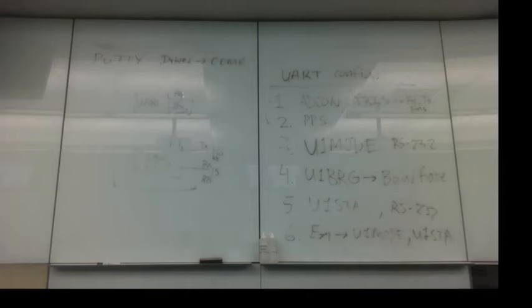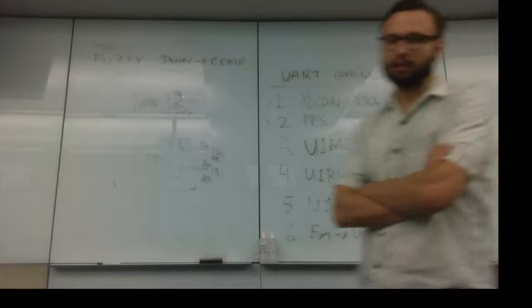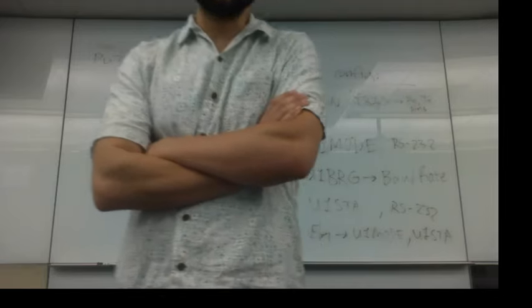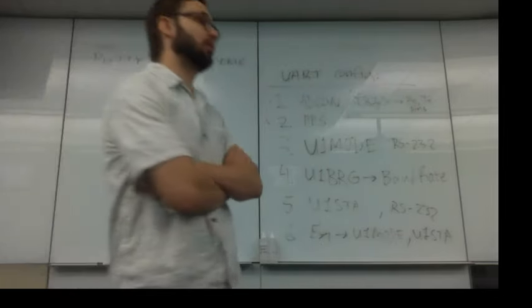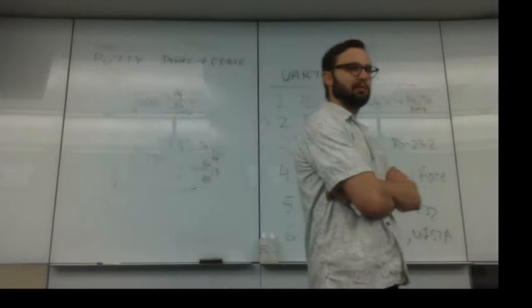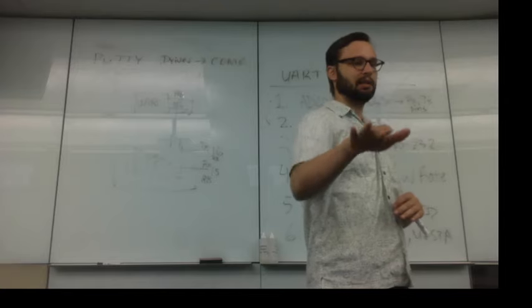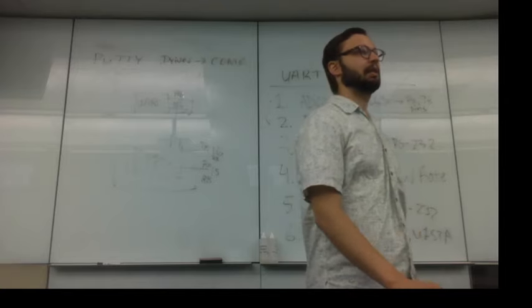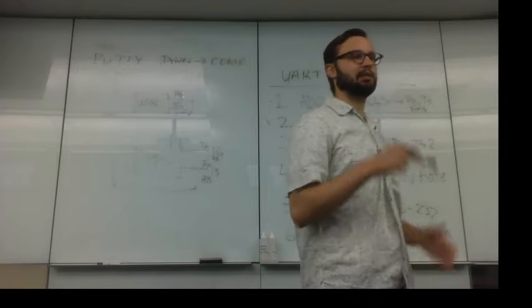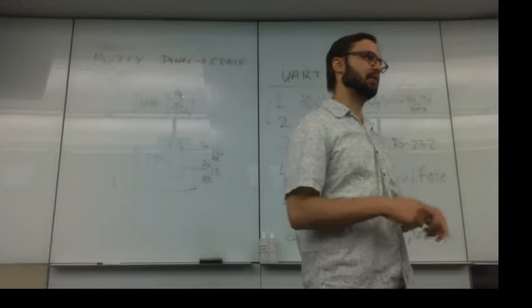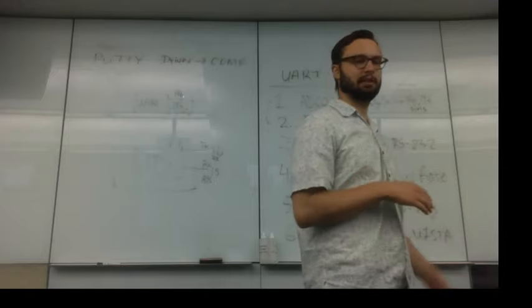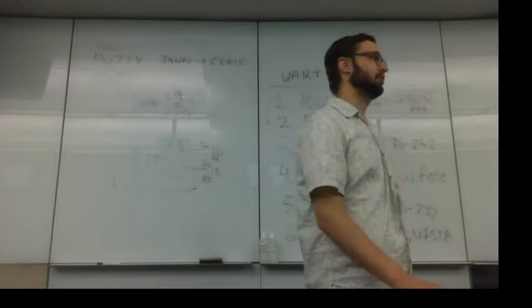The interrupt flags are pretty useful when you're writing code. There's something called transmit buffer full status bit, which will be set to 1 when you write the transmit buffer. That's when you send something in the transmit buffer. It doesn't necessarily mean that the transmit buffer has been shifted out the TX pin. It just means in your code you wrote to it, and so that bit will be set when you write to it.